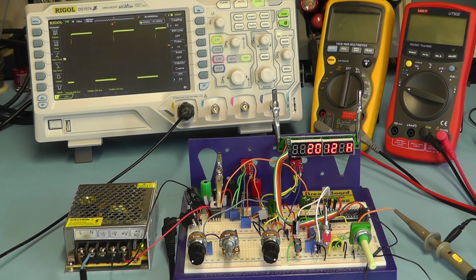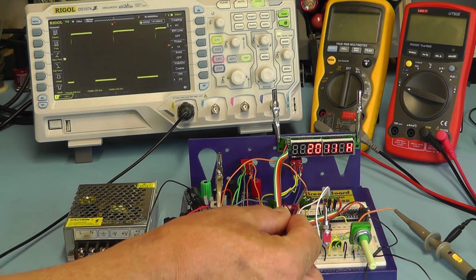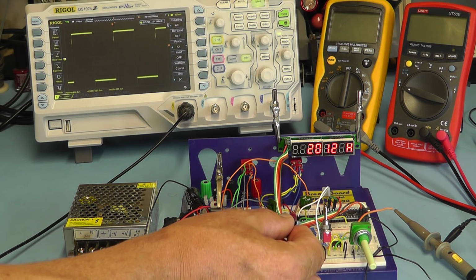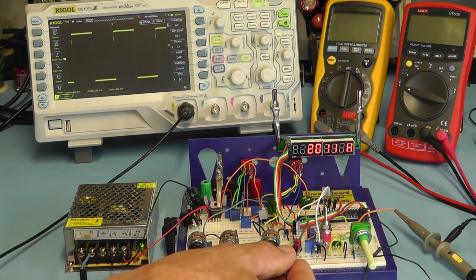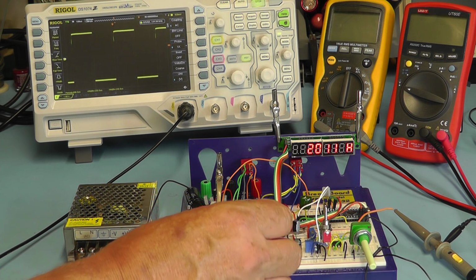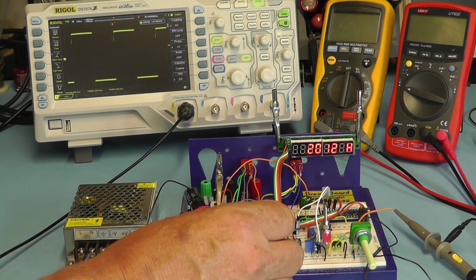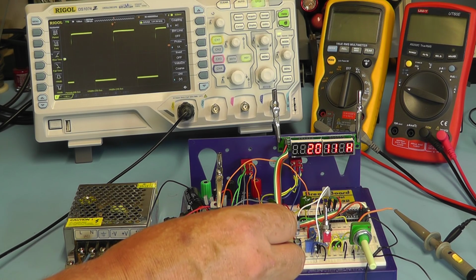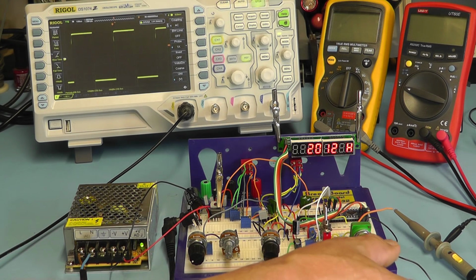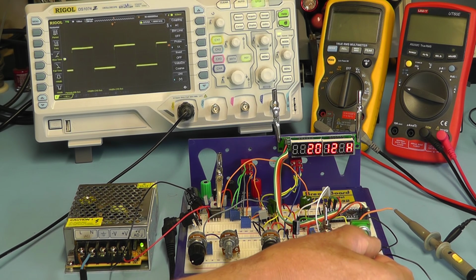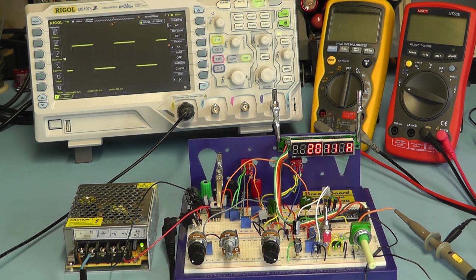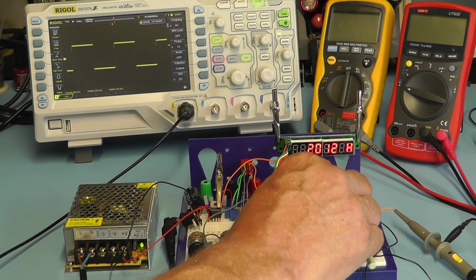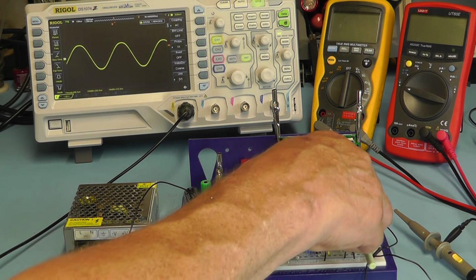There we are. So we need to have a little isolating capacitor coupling the square wave signal to the operational amplifier, and that's then allowing us to control the gain of the stage to give us our 6 volt peak to peak. Now the gain control we can simply use to set the output level, and it should be the same for both the square wave or the sine wave.